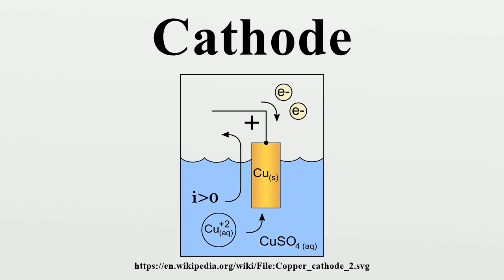Thoriated tungsten. In high-power tubes, ion bombardment can destroy the coating on a coated cathode. In these tubes, a directly heated cathode consisting of a filament made of tungsten incorporating a small amount of thorium is used. The layer of thorium on the surface, which reduces the work function of the cathode, is continually replenished as it is lost by diffusion of thorium from the interior of the metal.